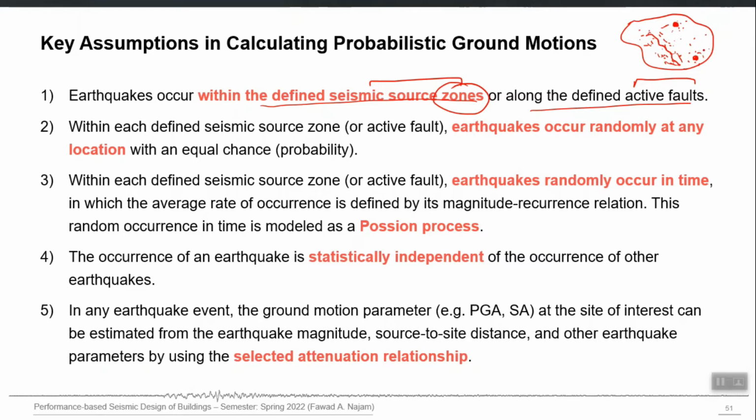Still there will be some past earthquakes which you cannot associate with any particular fault or a particular volcano, for example. Still there will be some earthquakes whose cause you will not be able to find, you will not be able to associate them with any particular fault, because they may lie very far from a particular fault or for some other reason. For those earthquakes, you will make area sources or source zones. I will use the word area sources, which is more convenient. So I will make some area sources like this,